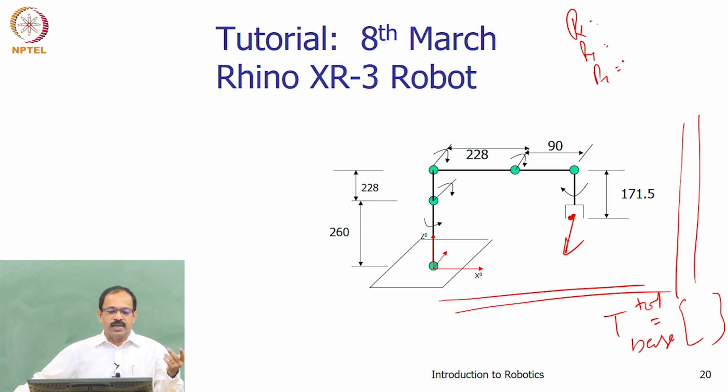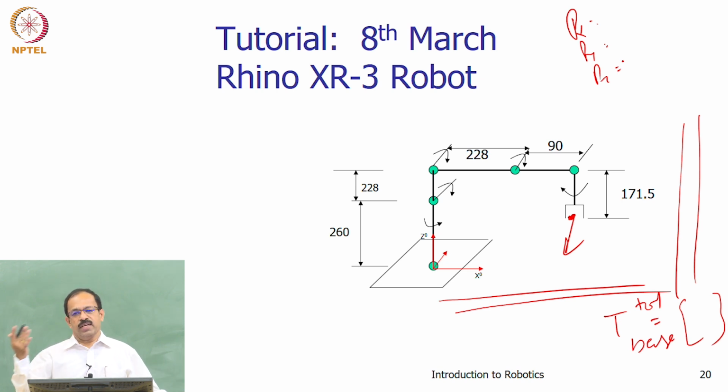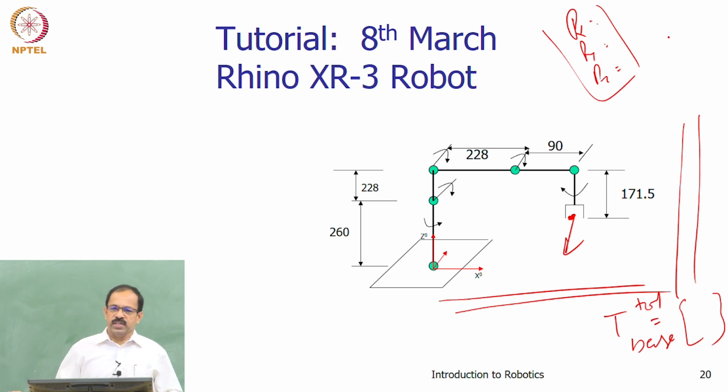So basically, that is what will help you to find out the workspace of a manipulator. Once you substitute the value of theta, for any value of theta, you should be able to get the position and orientation of the tooltip. So by sweeping the joint angles, you will get all the points that the robot can reach. Then you will get that as the workspace of the robot. Okay. So questions will be released by tomorrow. You have to submit the answers in Moodle by 18th.